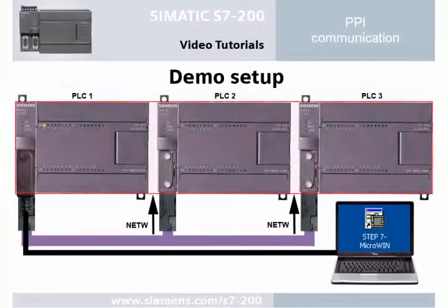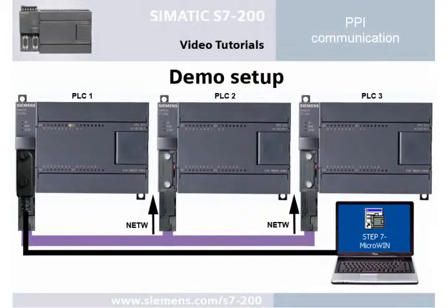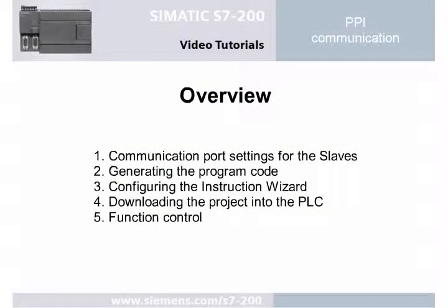As a task, a running light via 3 PLCs shall be configured in STEP 7-Micro/WIN. The running light concerns the respective output byte 0 of the PLCs and occurs bit by bit, rising from PLC 1 to 3, and falling in the PLC sequence 1, 3, 2. PLC 1 represents the master PLC, which writes to the output bytes of both slave PLCs via the NetW function. The NetW function is configured using the instruction wizard in STEP 7-Micro/WIN. The task is divided into the 5 following steps.